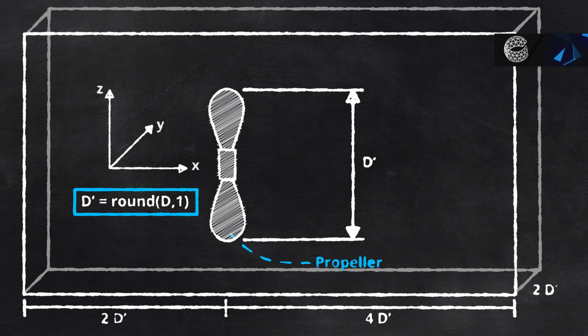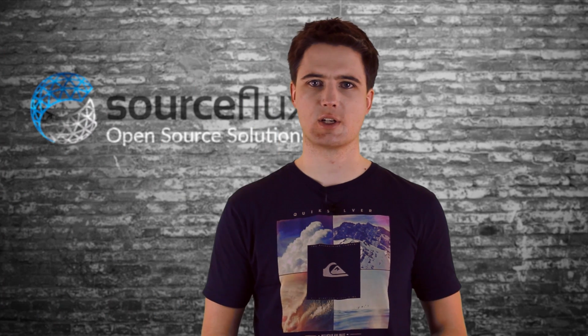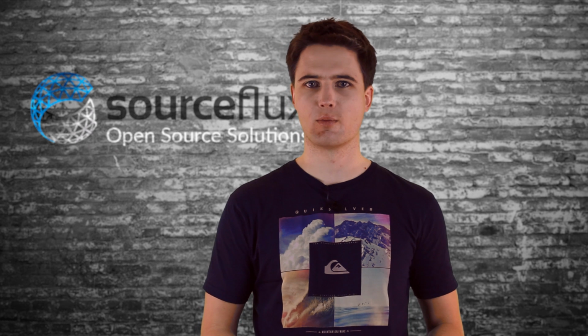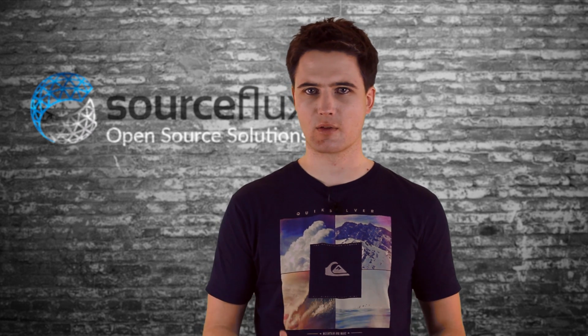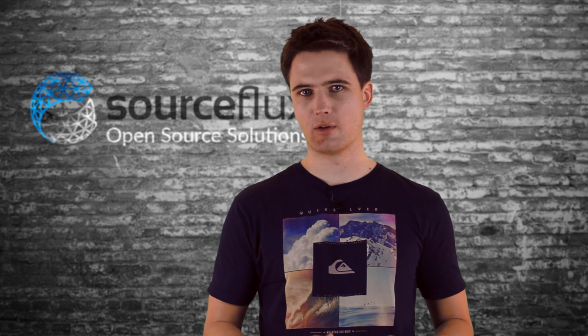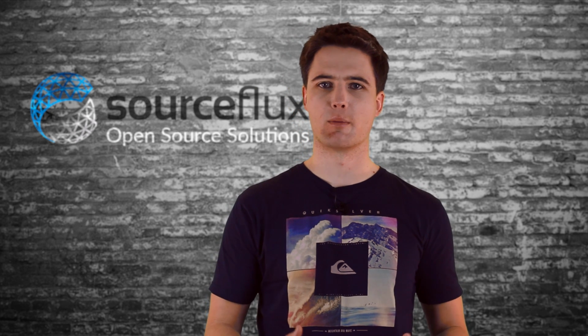Similarly, we are going to have a distance of 4D' between the origin of the propeller and the boundary with the highest x value, which is going to be called xMax. The remaining outer boundaries will have a distance between the respective outer boundary and the origin in the respective direction of just 1D'. Of course, this is way too small for a proper simulation, but this tutorial solely describes how to mesh things and not how to simulate the propeller properly.